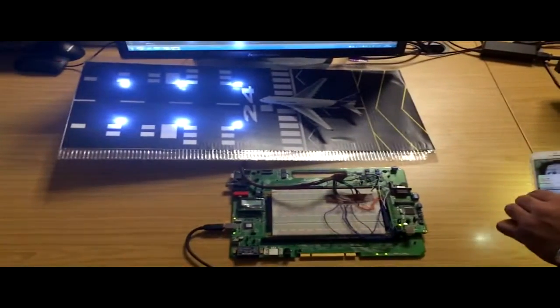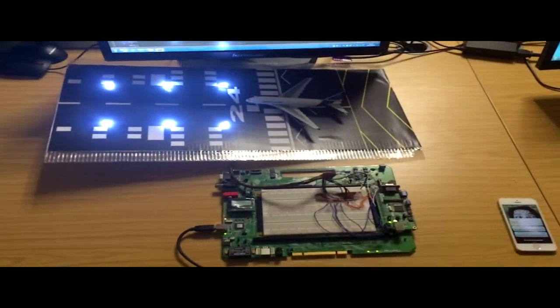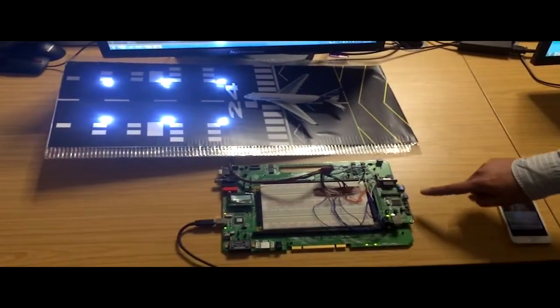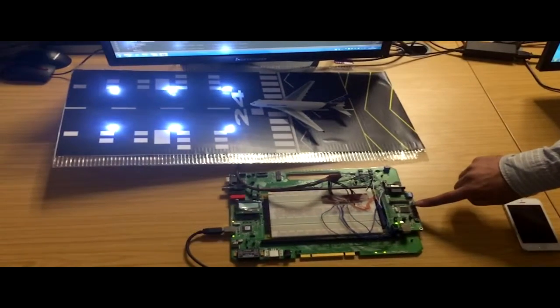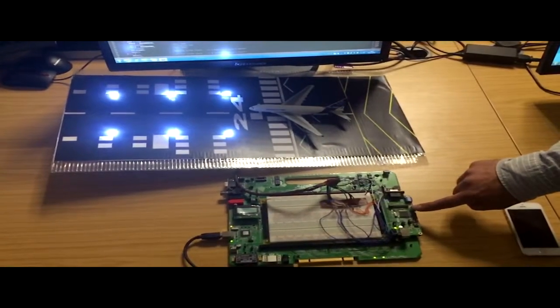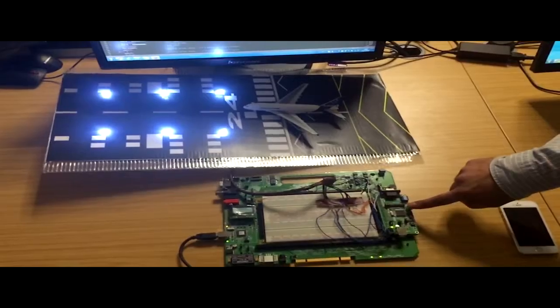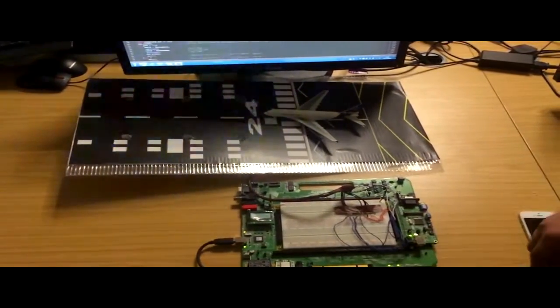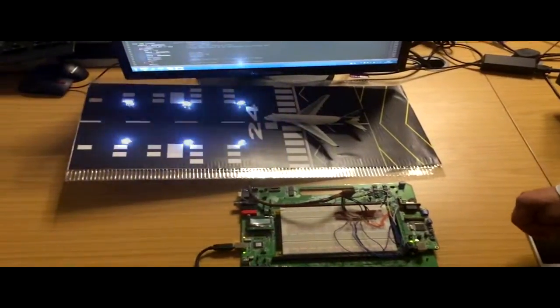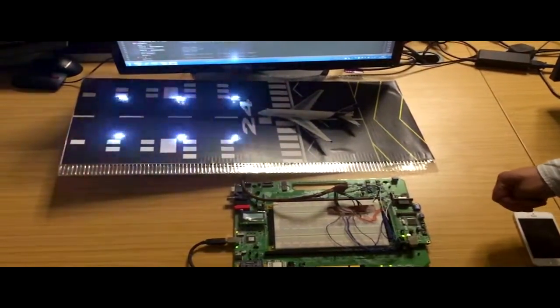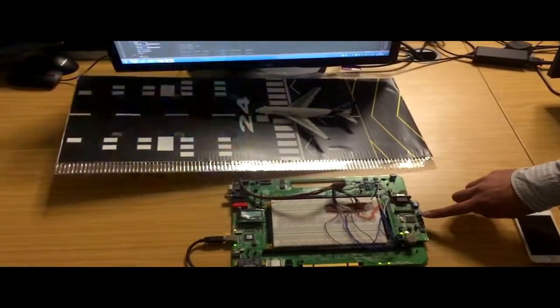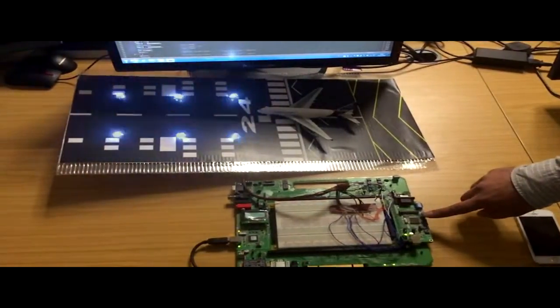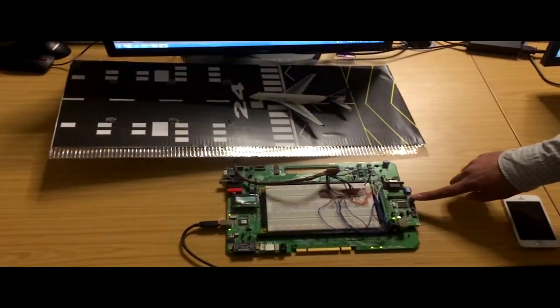Again, even in the automatic mode, if you turn down the potentiometer which simulates the temperature, the safety measure for less than 5 degrees works. So I turn it down to the minimum level, which is less than 5 degrees, and again the warning lights start flashing, which works in any mode: in automatic mode, in manual mode, and if the system is completely off, this safety measure works.